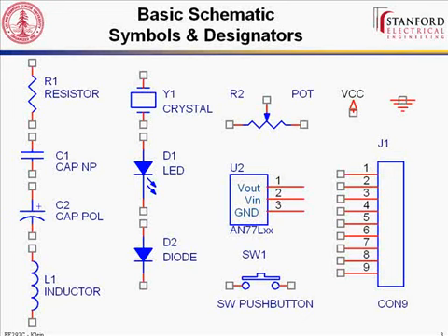Now you notice that all of these components have little square blocks, or at least a lot of them do, at the end of the net. And that just indicates a place where you can tie off a net or a wire. And some of them don't, like this voltage regulator designated U2 in the center. Don't worry about that. But if you see one of these little square blocks, it just means that that's a point you can tie off to. You also can tie off to the pins in the voltage regulator. It just doesn't have the square blocks. So those don't have any particular special meaning.